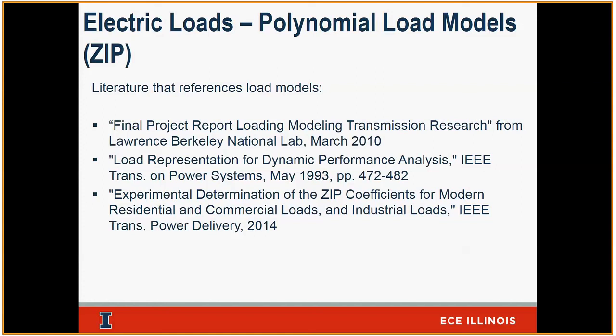No, go ahead. So harmonics basically pollutes the power factor, right? And you can get the power factor from AMI. That's what you mean. We could, yes. So you could technically analyze the power factor and study the load profiles, because you already have a ZIP model of that load, and determine how much of the power factor is getting affected due to harmonics. Absolutely. We just don't have the manpower to do it.